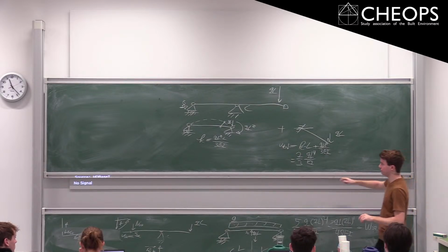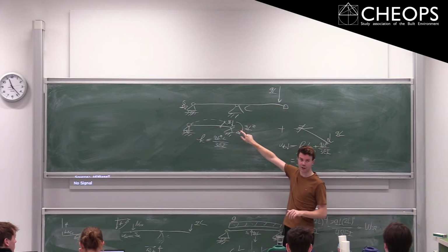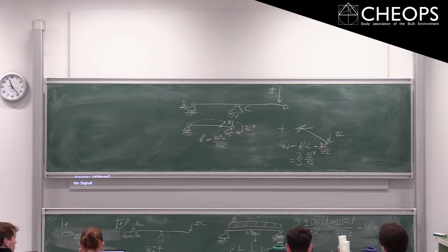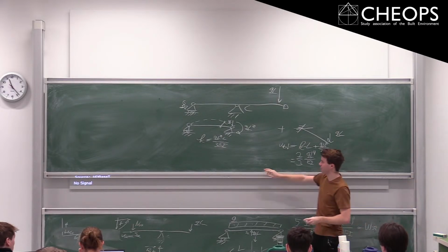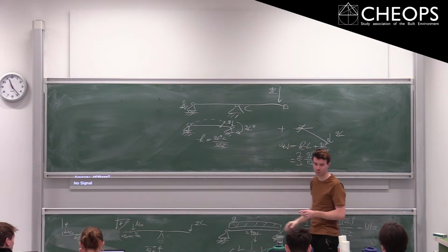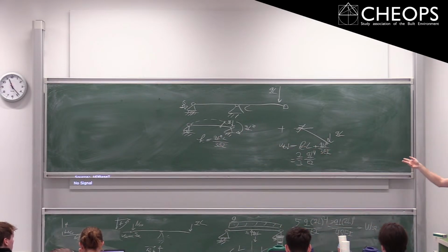Does that point load here cause any rotation in that point? Yeah, it will just go straight, will be supported directly. So indeed, because we're only looking for this rotation actually, we don't bother about any movements over there. That point load will actually do nothing in any case, right? It will just be set to the ground straight away. So only the moment causes that rotation.